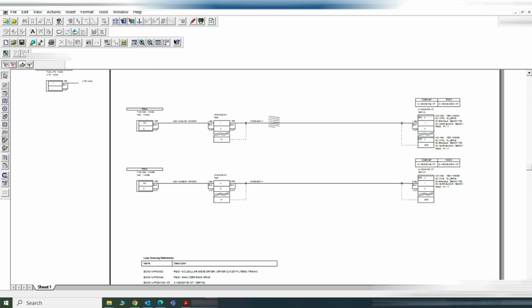So basically this is the conventional wiring. Whenever you have seen in the wiring module how you did the wiring, you created a device panel and a single pair cable that is already created during the instrument index preparation. So these portions you already did during the instrument index module, but the right side of this cable you need to connect with the junction box. So you have created a junction box in the wiring diagram, and again you have connected the second end, or you can say the right side of the cable, towards the junction box.